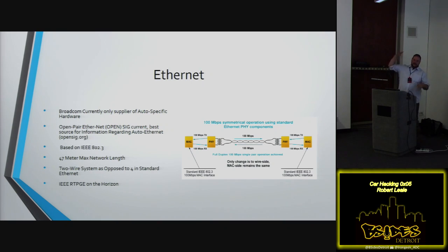They're going to connect the telemetry units with the head units so that they can do over-the-air updates, right? I mean, that's one of the big reasons: reflashing. Because of the problem of CAN bus, let's say you get into your car, you turn it on, and it says, hey, I got a new update for you. Would you like to apply it? And you hit yes. Then you have to wait 30 minutes for it to apply. People are not going to be too happy. They're not going to hit yes next time, right? So we really have to have a fast pipe that's going to allow us to send that data as quickly as possible between the controllers.